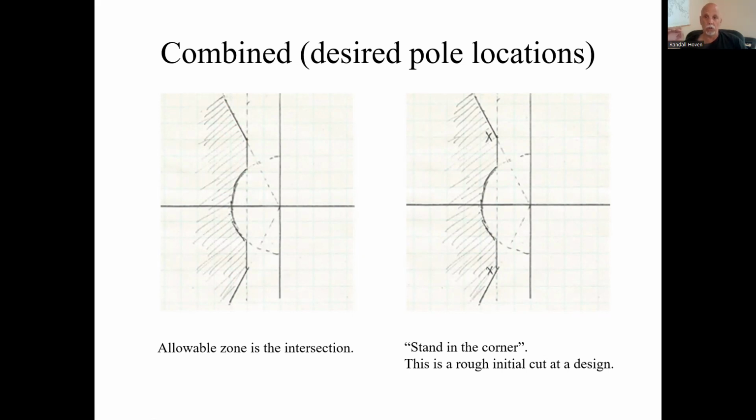Where should you put the poles? That's where you get to the art of it. They have to be in the allowable region. But you just don't want to say, oh, let's put them way the heck out here and be done with it. There are reasons we'll get to later in the course you don't want them further out than you need. And a rule of thumb, meeting any spec, never exceed the spec by too much. They'll end up paying for it somehow, some other way. So stay kind of close to the boundary.